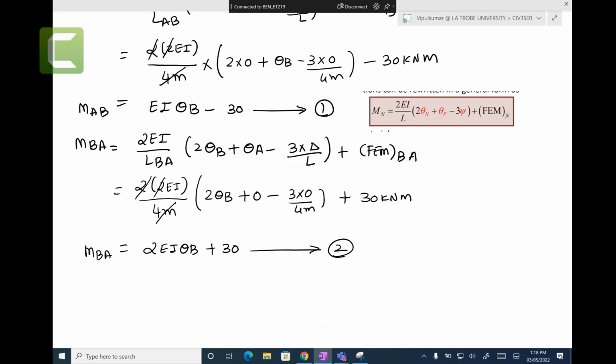So sometimes in structures, after a period of time, you may find settlements. Let's say you are an engineer and you got a job on a 30 year old property. This is the initial soil report, but after 30 years, it has gone down 5 millimeters. Possible. It's settled. So in those calculations, you might need to include that settlement.